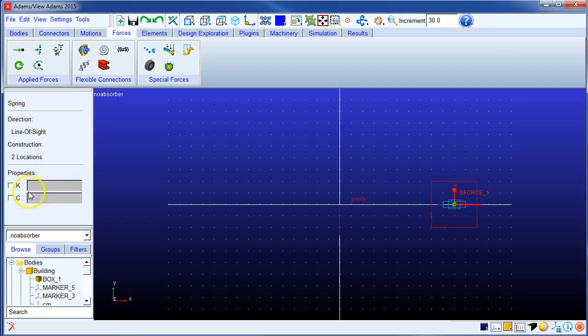So we're putting a spring on here, and there are different ways to build it, but I'm going to put in a spring constant of, and I think the project tells you what spring constant to use, I'm going to use a 1. This will be in default units, which I think are newtons and meters, so there'll be 1 Newton per meter. That might be a little too wimpy, but anyway.